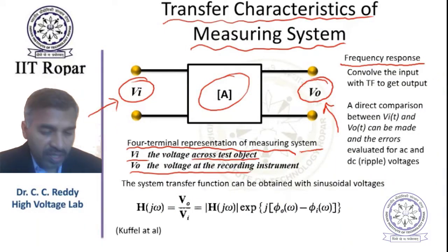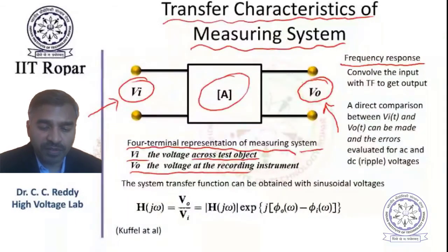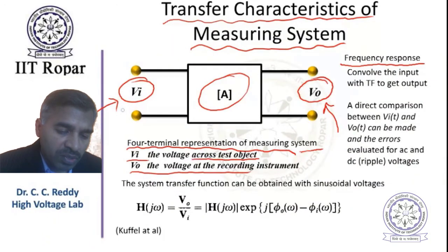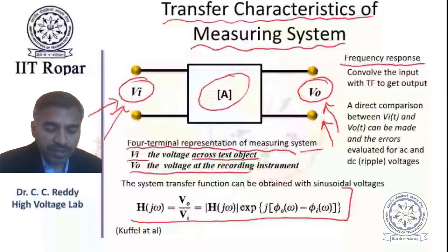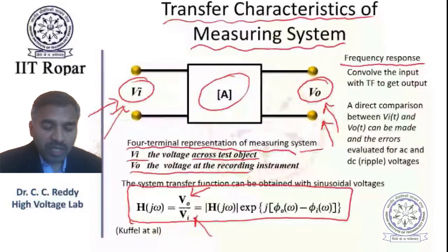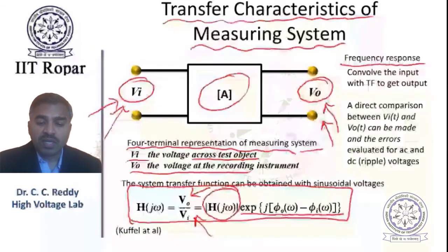Okay, so fundamentally, we have to study what the response of the system is at different frequencies. Yes, sir. As an example, any input, a sinusoidal function, can be given, and then the output can be measured at different frequencies, and then you can get a magnitude plot and phase plot, from which the transfer function H(j omega) can be obtained like this. This is the output function, this is the input, and in the frequency domain, this becomes the magnitude of the transfer function, and this is the phase angle of the transfer function. So this is how it can be obtained.